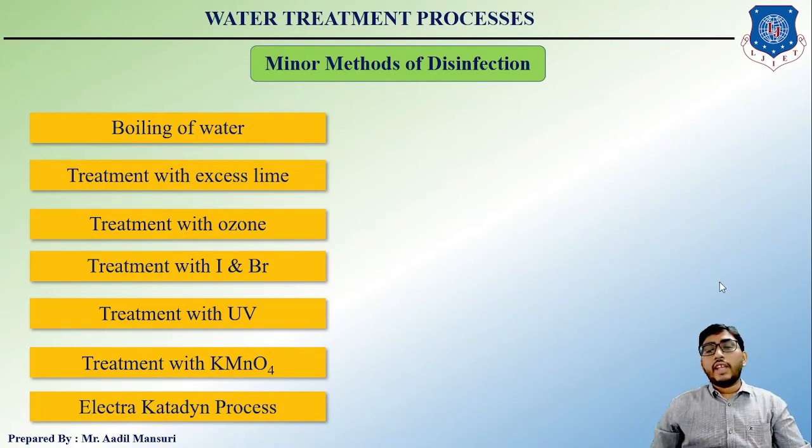Right? Talking about lime. Lime is generally used at a water purification plant for softening, right? That is reducing the hardness. Now, what is hardness? If the water is hard, then the foam forming capacity of water is less, right? So, hard water will not create a sufficient amount of foam when added to soap, right?